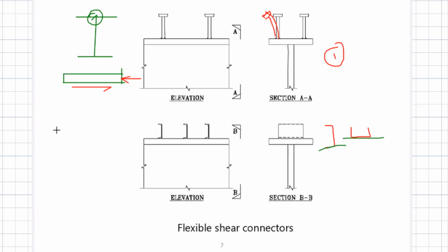Because of the high stress and more area, the flanges will have a lot of compressive or tensile force. So what we do is transfer the flange force across the interface of the flange and the web, and we design the weld. Very similar to that, if I draw the free body diagram of the flange and the interface, this is the equilibrium.